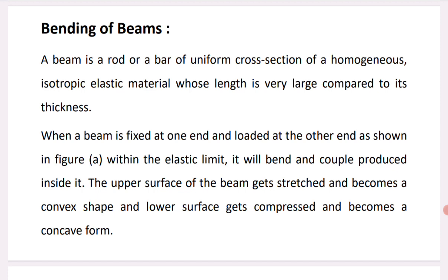Within the elastic limit, if it bends, the restoring couple produced inside it at equilibrium condition must be equal to the applied external couple. The upper surface of the beam gets stretched and becomes a convex shape, and the lower surface gets compressed and becomes a concave form.